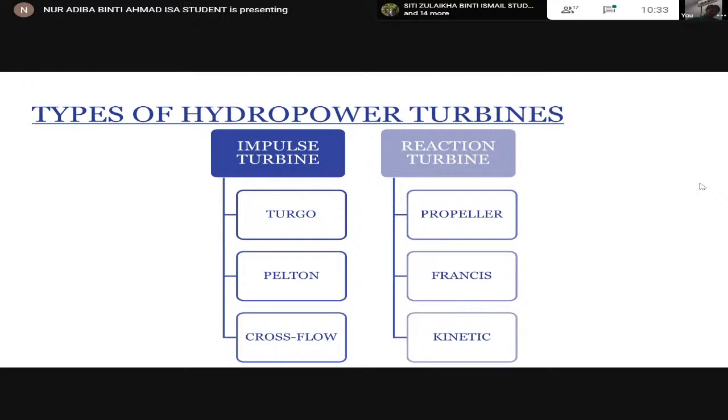The impact is it can still work for low discharge or low flow rate. Even though it has a low flow rate of discharge of the water based on the precipitation, we can still use Pelton turbine. The maximum efficiency is 90%, and we are using 75%, so there is no problem if you use Pelton turbine. So there's no impact.